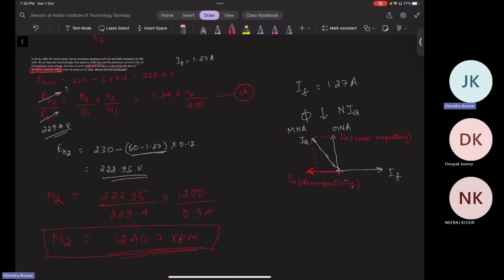First, you cannot deliver constant power at all speeds after base speed. Below base speed, of course, your power is increasing. At base speed you have your rated power, and after base speed maintaining it is a bit tricky, but you can maintain it up to a certain speed. That is why it is known as the constant power speed region, a very important factor when you design a machine for EV applications. But it has some limitations.